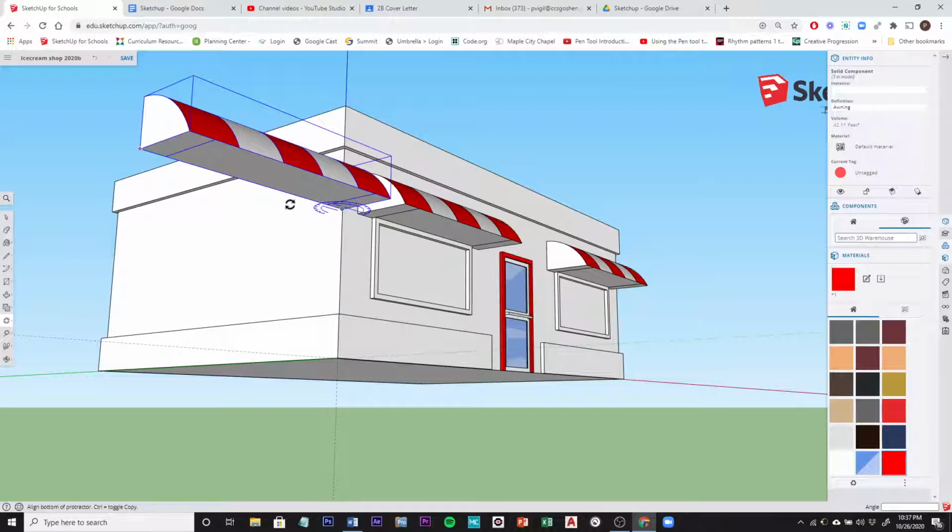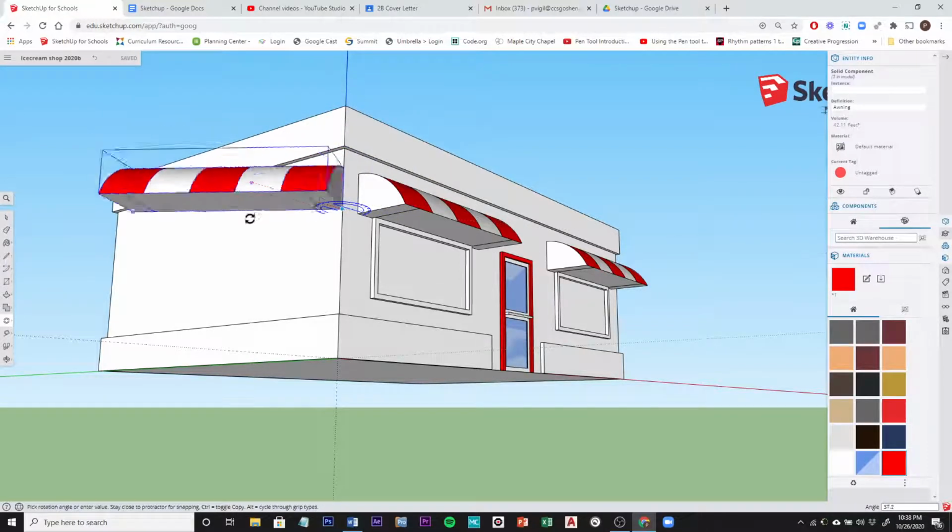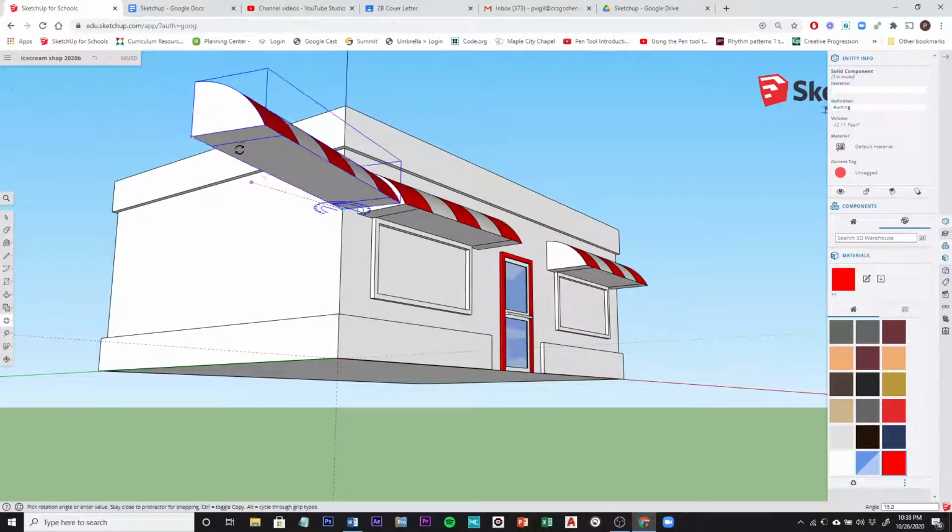The next thing is your reference line. So on here I could choose this line or this line as my reference line. It doesn't really matter which one. I'll choose this one because it's probably visually the easiest to see. So any point along this line would be a good reference point. So I'm basically just saying I'm going to grab this object along this line. So I clicked one time, and now I can begin to rotate it